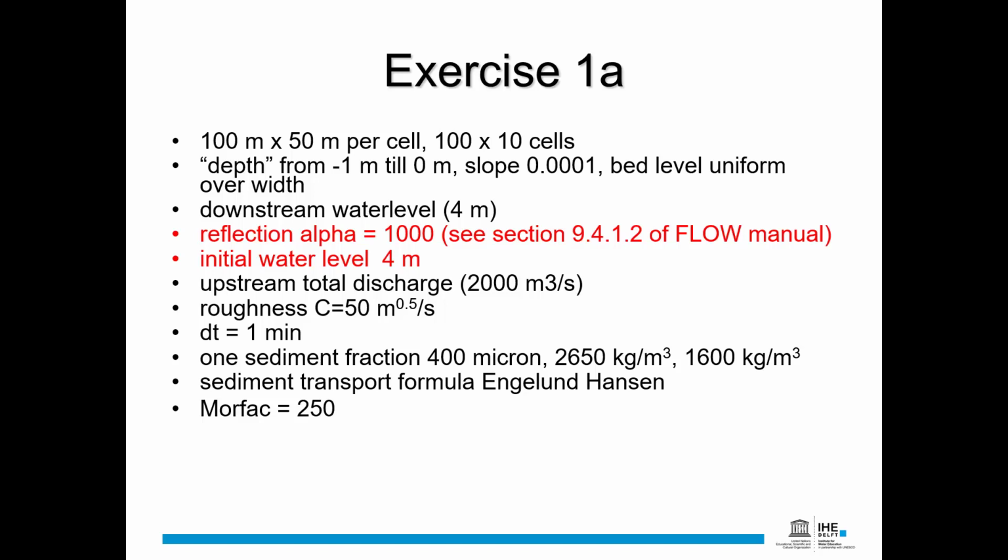And downstream, we want to have a boundary condition of 4 meters of water level, and upstream a total discharge of 2000 cubic meters per second. The rest of this slide shows the other parameters that we want to put in our model setup.